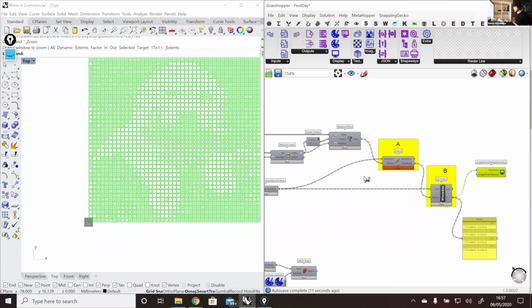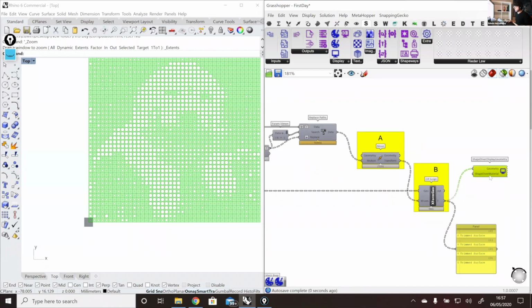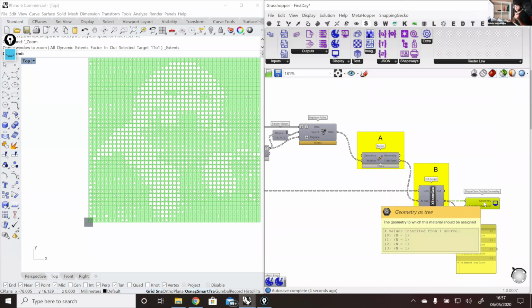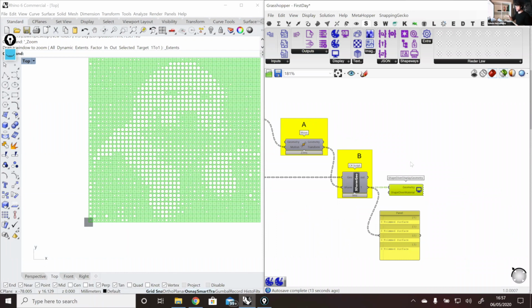The big difference here is that we are sending to the online application just 4 pieces of geometry, which are very simple. And the transformations happen in the viewer, in the browser. Instead of sending all of this very heavy geometry, all of these faces, to the browser, to the cloud application, all at once, which takes time to be sent, transferred, and downloaded by the browser, we are just downloading 4 surfaces and making the transformations inside the viewer, inside the cloud application. That's way faster because the transfer of data is way faster, and we are creating just 4 meshes in this case.